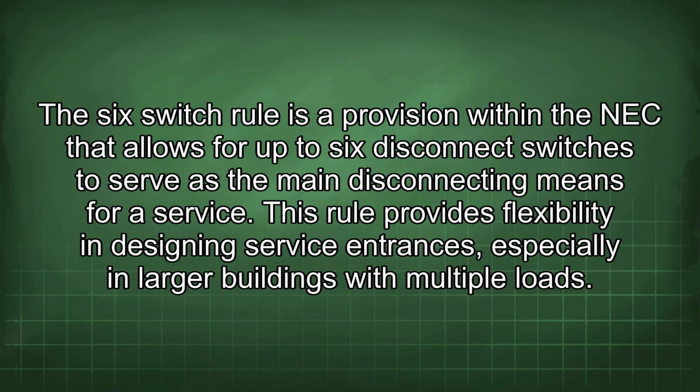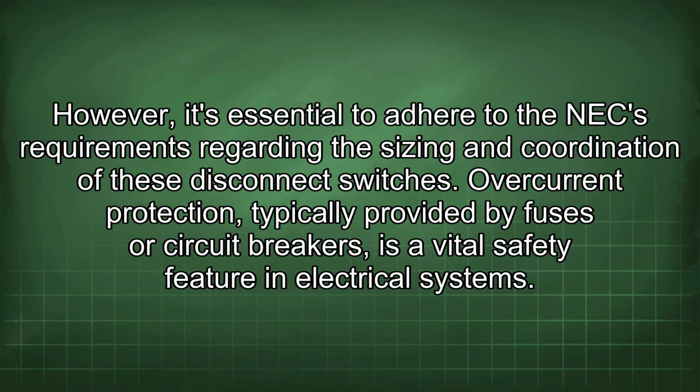The 6-switch rule is a provision within the NEC that allows for up to 6 disconnect switches to serve as the main disconnecting means for a service. This rule provides flexibility in designing service entrances, especially in larger buildings with multiple loads. However, it's essential to adhere to the NEC requirements regarding the sizing and coordination of these disconnect switches.